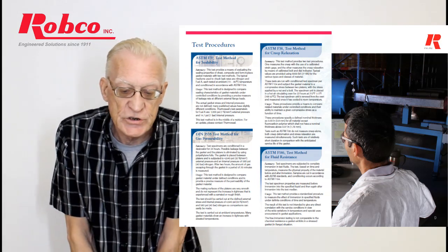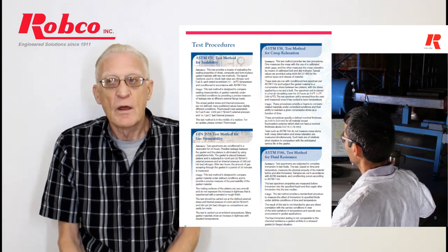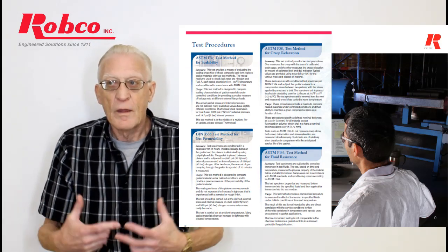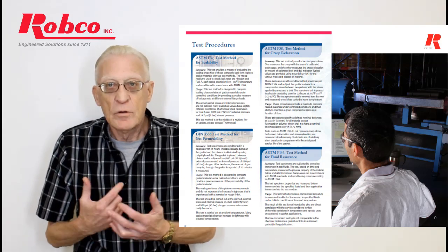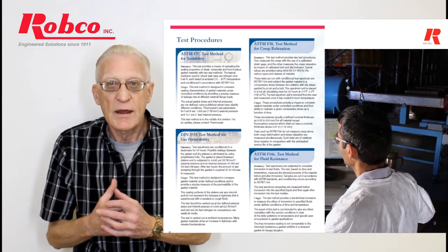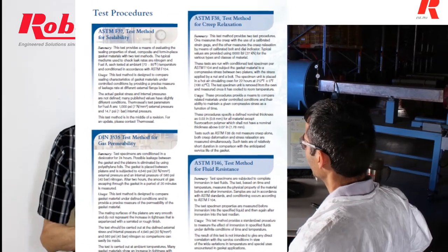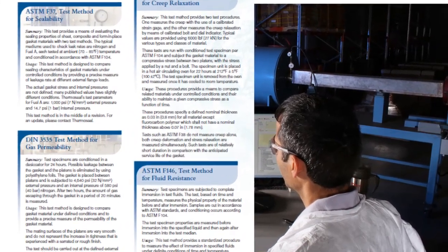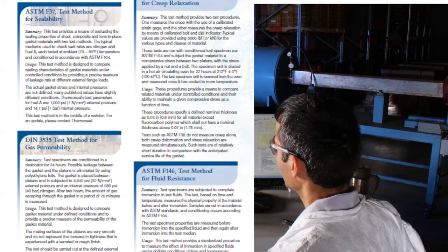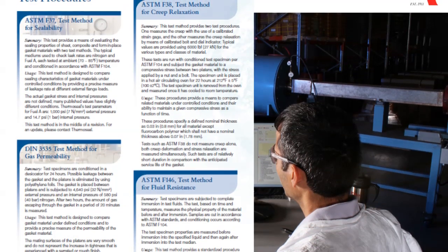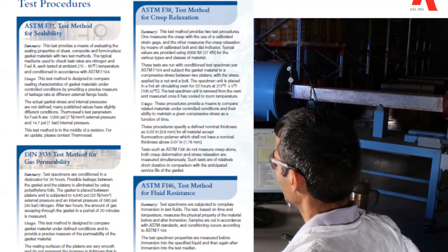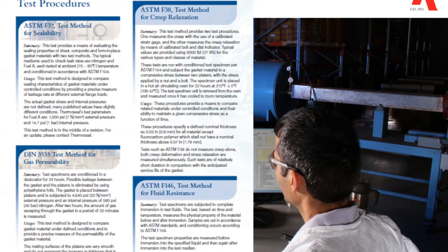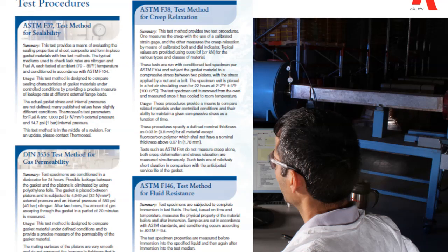Some of the test procedures, as I had mentioned, everything is written down. The Bible for gasketing is the ASTM, American Society for Testing and Materials, F-104. That's the book. So page 1 is this test, page 2 is that test, and exactly how to do it so that all manufacturers, Garlock, Klinger, Durabla, whoever, all do the same thing to their gaskets and give you a result.